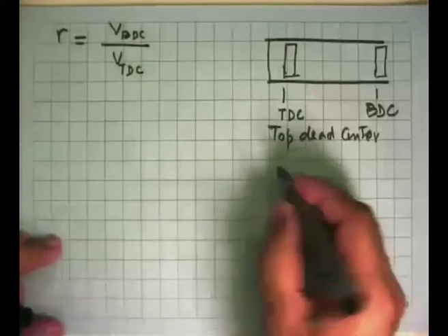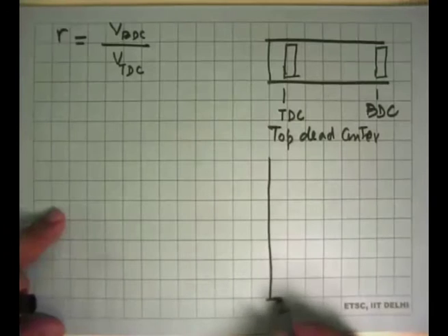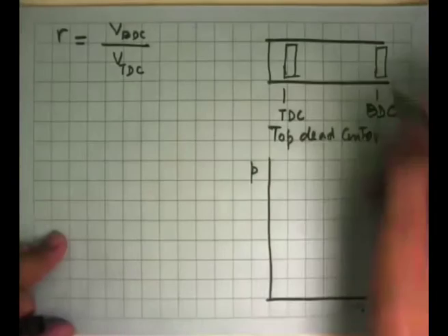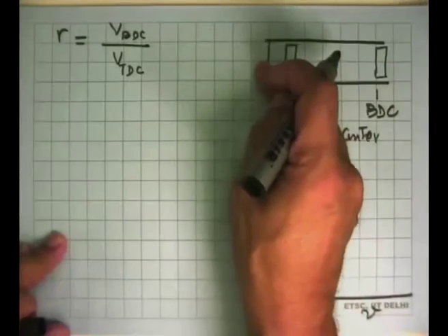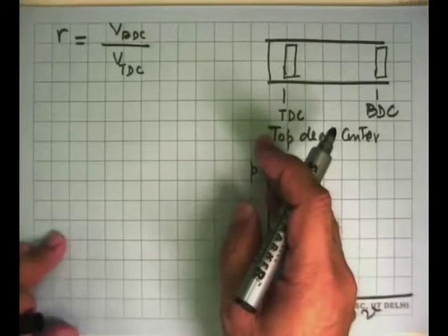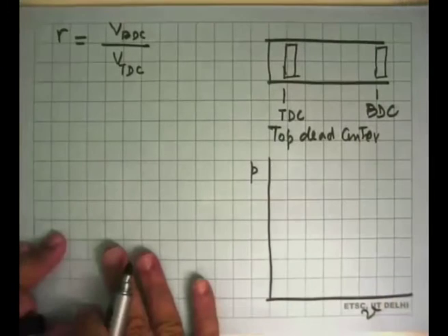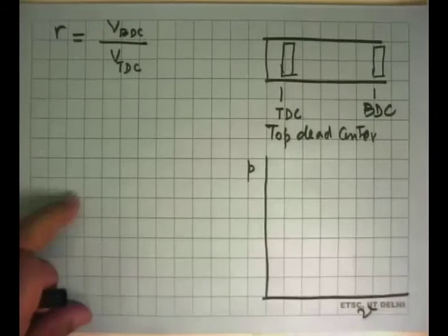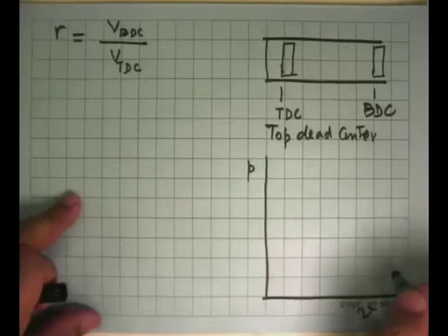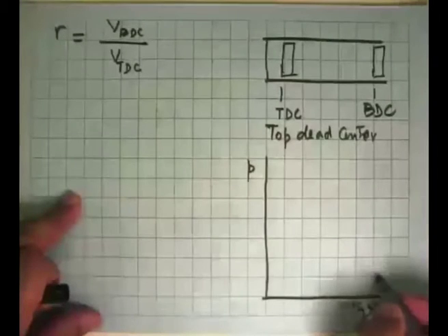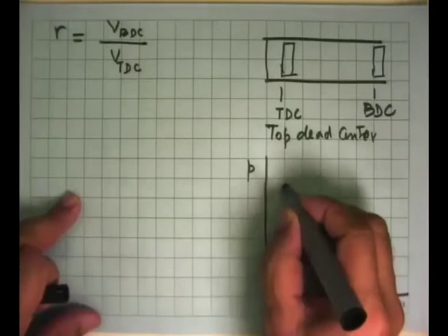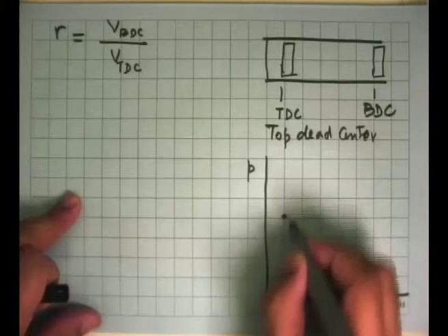And if you look at the complete analysis of this cycle, the air standard Otto cycle will look like this. I am plotting V here and pressure here, and we ask, when the piston goes up and down, how does pressure vary, what is heat transfer in each process, and what is work transfer in each process. This is what we want to know. So in the compression process, we start from here and we reach a point over there.